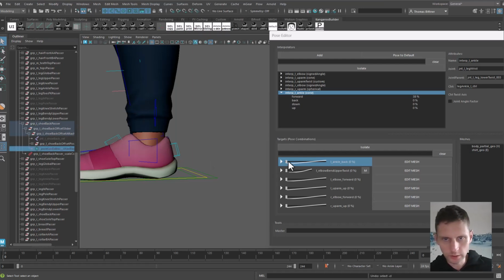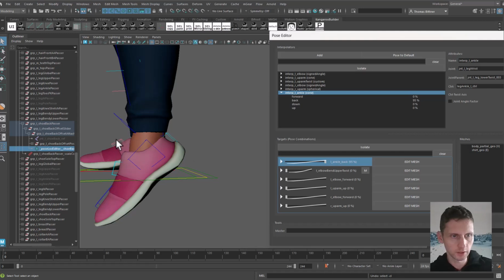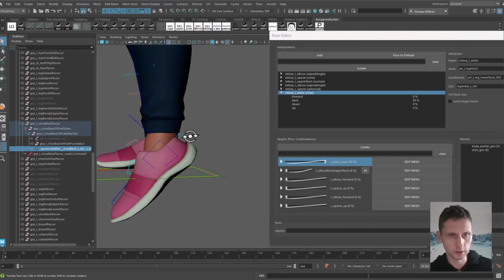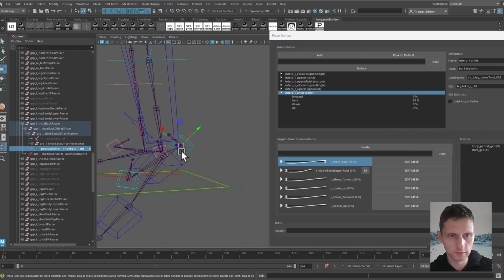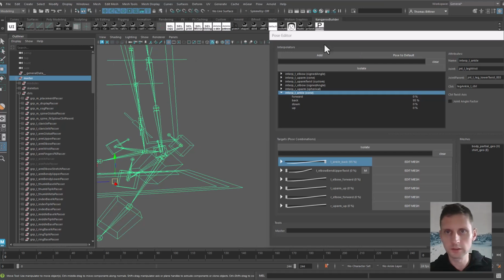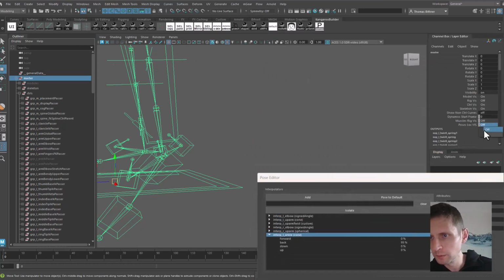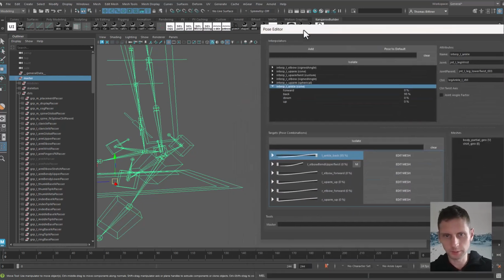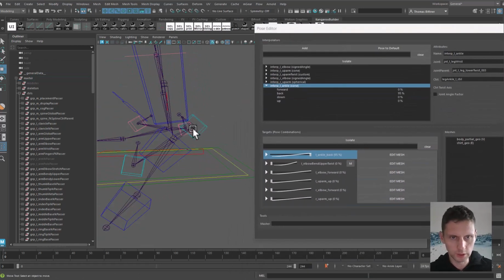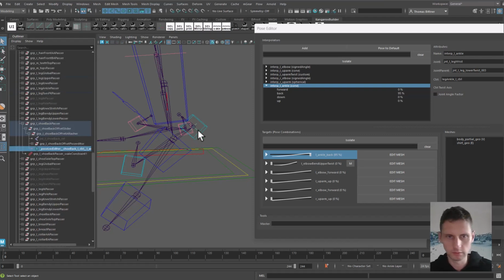And if I actually go into the pose, then it shows it, the visibility turned on. You can see it now, or you cannot see it. That's because pose lock needs to be on. Sometimes you have this on the top group, sometimes not. But if you don't see it, then check for the attribute, and now you can see the pose locator.